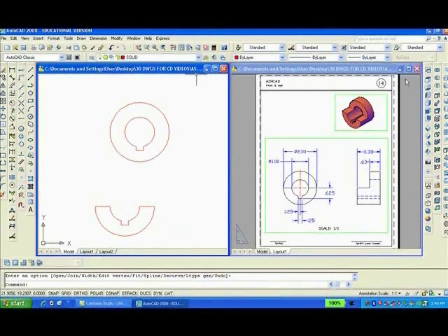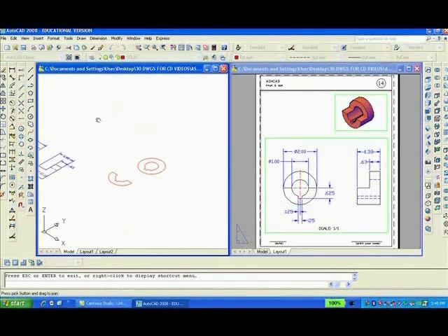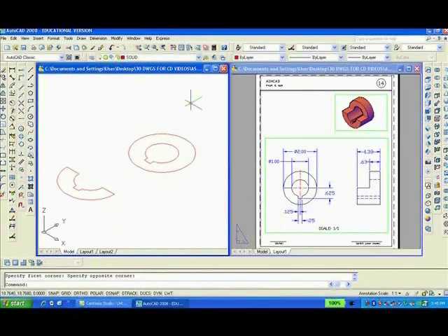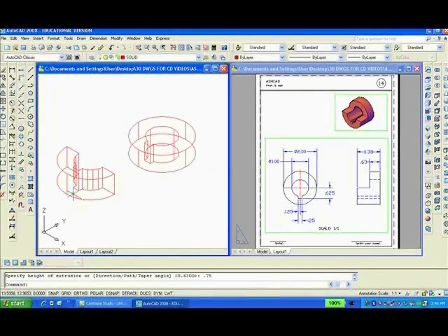And we're free now to move into southeast isometric view, to pan over and zoom with the window to enlarge what's going to be the solid. Now you'll want to type EXT to extrude, and we'll select this portion. That's going to be a height of 0.63, enter. And we're going to extrude this portion and that's going to be a height of 0.75. Enter.